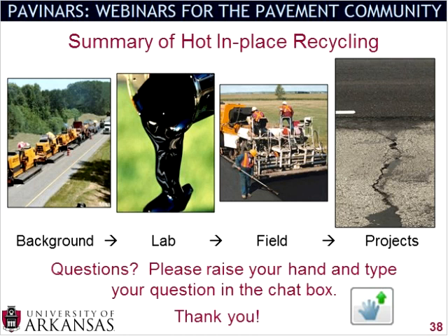But again, this is another good example of a reason why I don't think there's any established mix design or established construction procedures, because there are so many variables going on here. Unlike, for example, cold-in-place recycling, where you may have raveling problems and a surface course is almost required, those types of issues don't occur with hot-in-place recycling, because oftentimes you're adding in either an asphalt emulsion or an asphalt cement, so you're able to restore to a typical surface course.